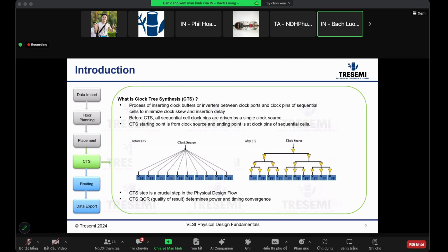So tracing means when the CTS process starts, remember, it starts from a clock source and goes through the clock network, so it has to trace through. Here before anything happens, it'll trace through this clock source. Okay, here's one sync point. It'll stop here. In between, they're all the clock trees, right?